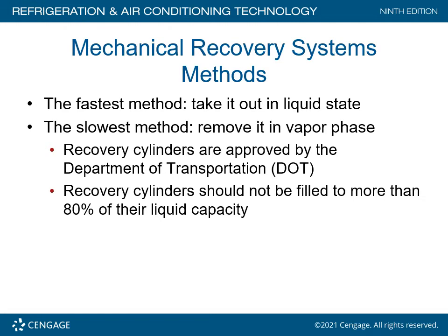If you like to sit around and drink lots of coffee, recover refrigerant in vapor, and you'll be there for 1 or 2 hours, guaranteed. Recovery cylinders are approved by the Department of Transportation. They are stamped with a DOT number. Recovery cylinders should never be filled more than 80% of their liquid capacity.